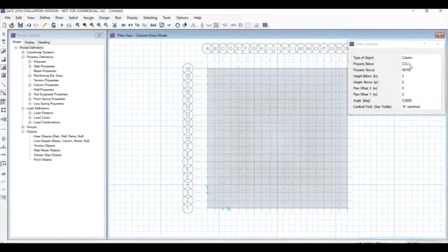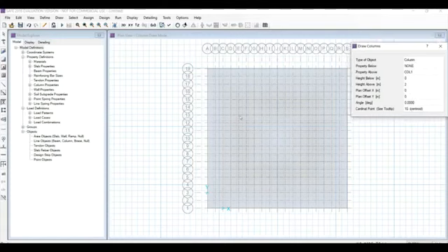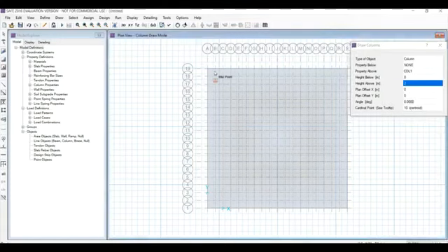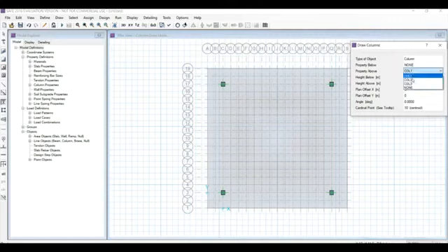Column 1, below is none. Make sure that below is none. Above is column 1. Height below is 0. Above is, let us assume 2 meters of plinth beam level. Then go for 2, and then draw the column. Let us assume that there is 2 meters distance from each and every center for column 1. Column 1 is completed. Now draw column 2.